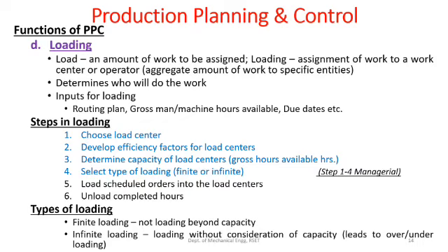For example, in a route plan, you are required to turn a particular component. Now, in the turning department, you might have multiple lathes that are available for turning purposes. So, amongst the different lathes available, which is the one that you assign that particular work to? So, that is your load center. So, you have to choose your load center, that is where the work will be carried out, or to whom that work will be assigned.